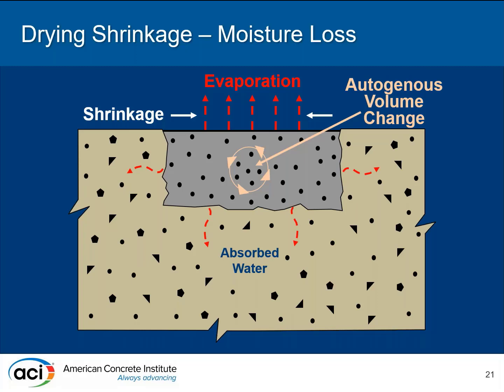As a quick refresher, shrinkage occurs when you lose water in your concrete after it's set and hardened, but it'll continue to lose water through evaporation or absorption, and your concrete wants to get smaller. So you need to think about that as part of your repair design process, picking the right materials so that they can behave together.